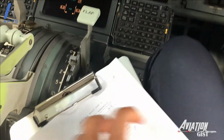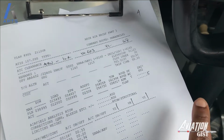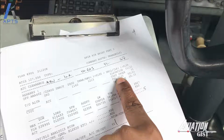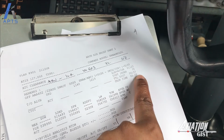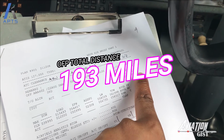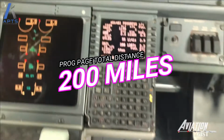For instance, if the total distance from Abuja to Port Harcourt on the OFP reads 313 miles, the distance on the progress page should read at least plus or minus 10 of that distance. In this case, the total distance on the OFP reads 193 miles, and that of the progress page, 200 miles. This is an acceptable margin.